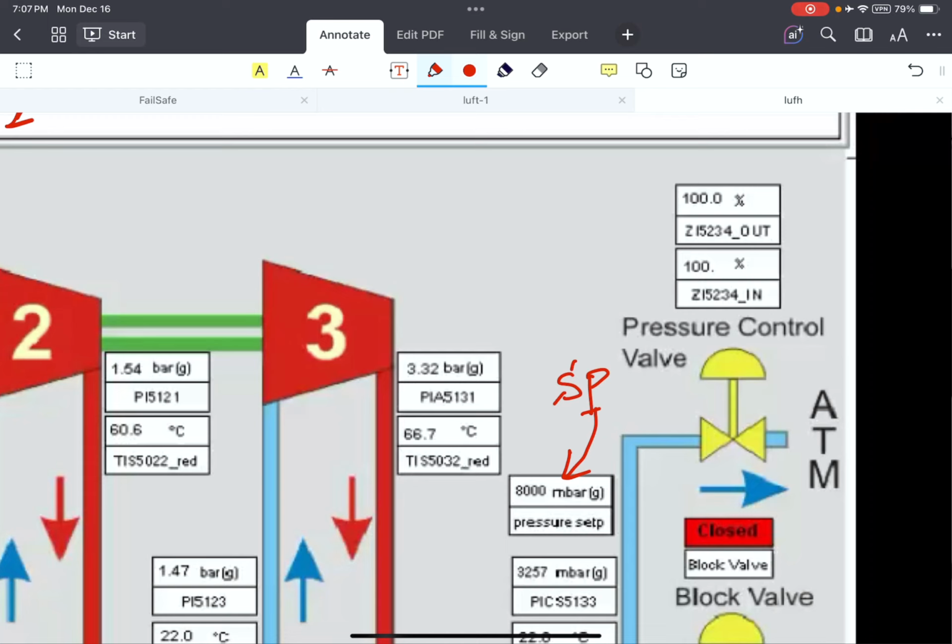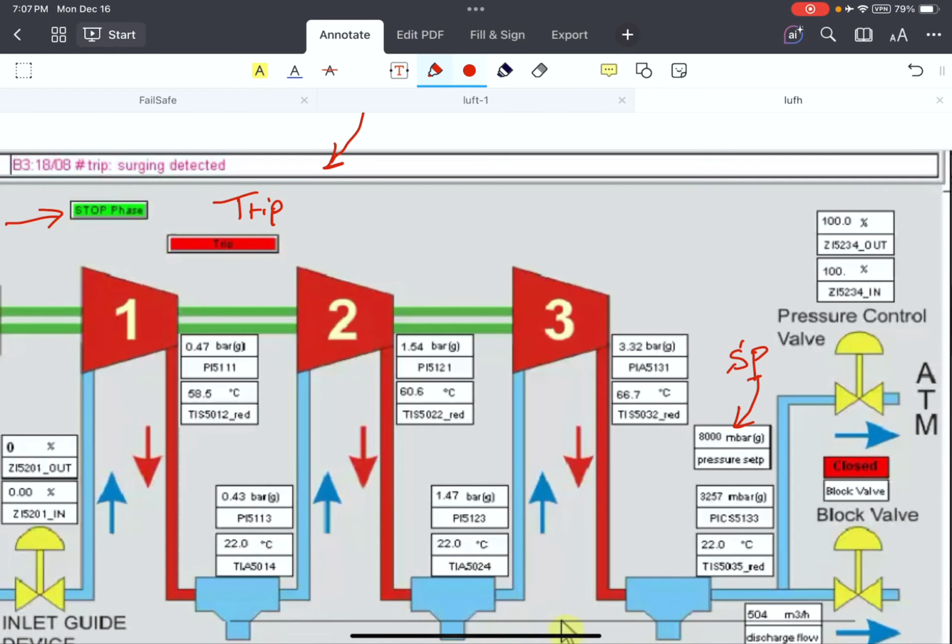In case of safety, if we want to manipulate the safety variable inside the failsafe CPU, it's possible to be done from WinCC, but there are some special failsafe commands from WinCC to run and to initiate. So there are many other options, like user authentication to permit internal variable of CPU manipulation, or even run, stop, and change variable inside the PLC.